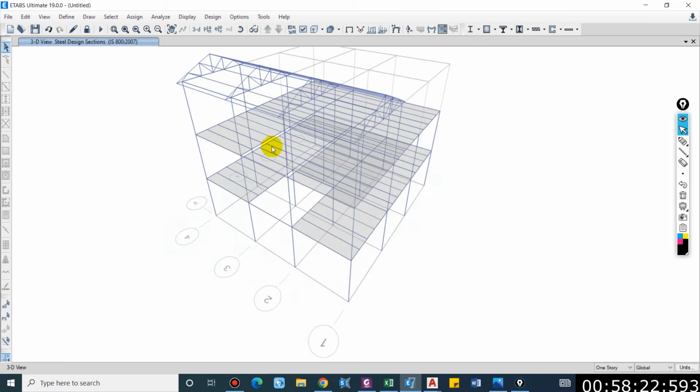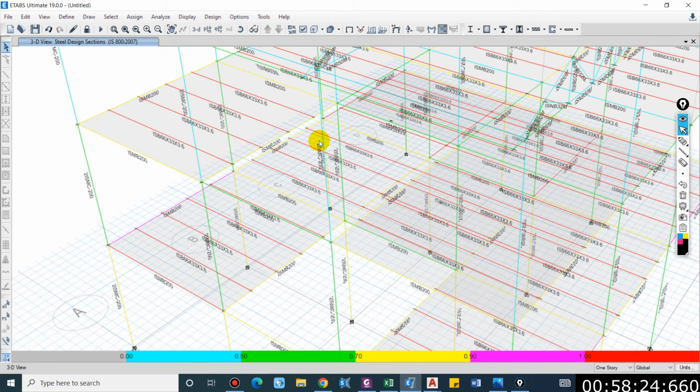So you can see the stringer beams have failed now. The basic idea here is that 100% of the load from the slab is transferred directly to the supporting structural members. The deck doesn't possess any stiffness, doesn't possess any resistance for moment and shear. That is, we are just applying the load on the stringer beam. That is not realistic.